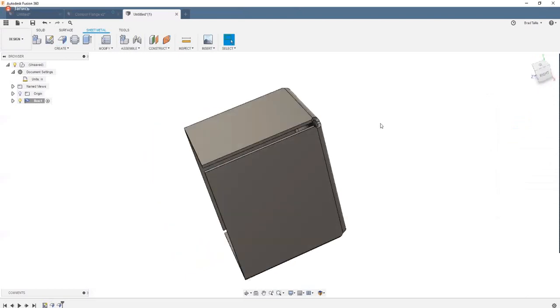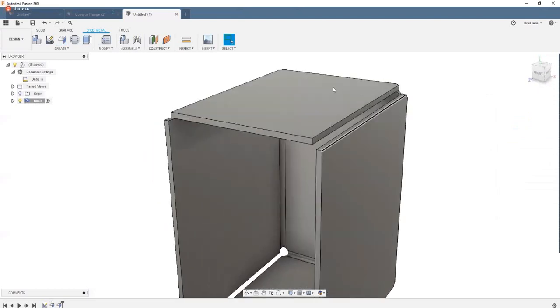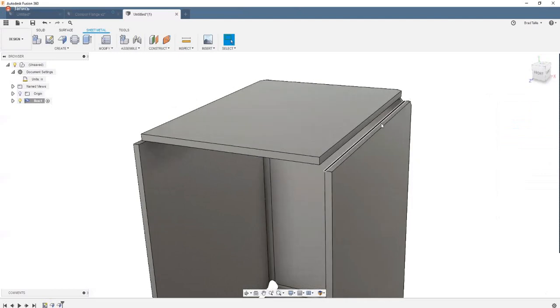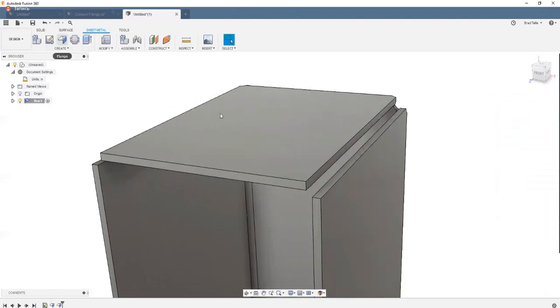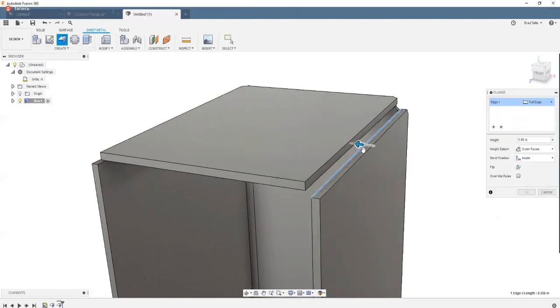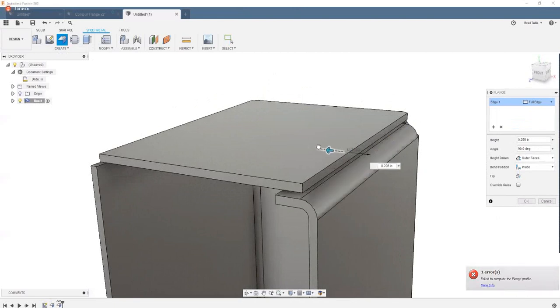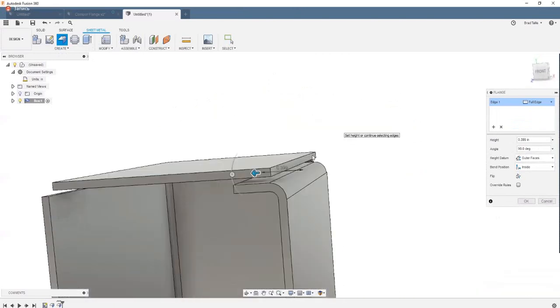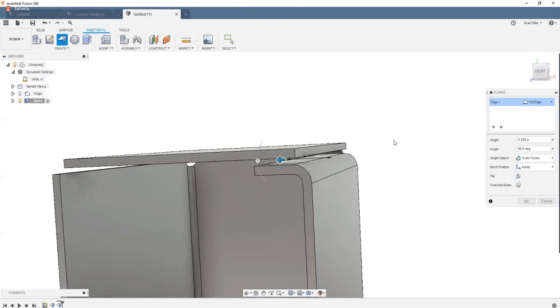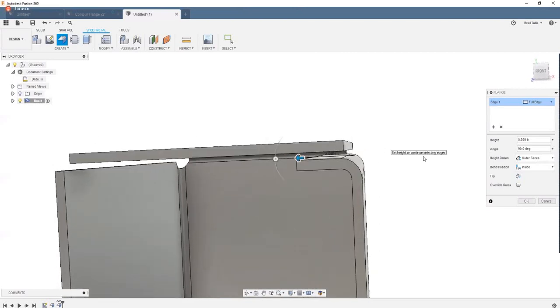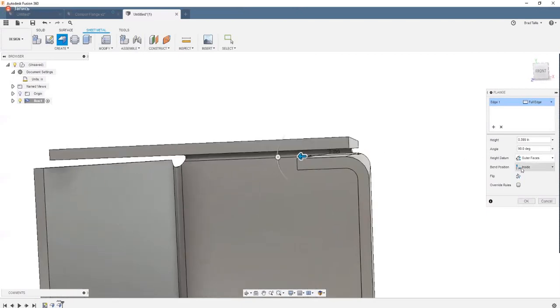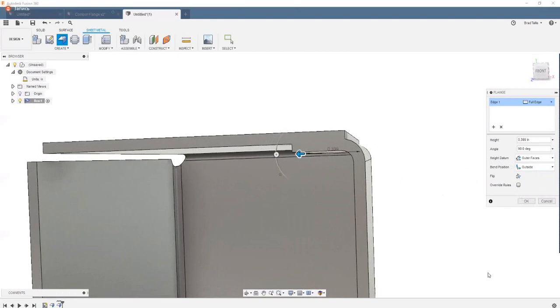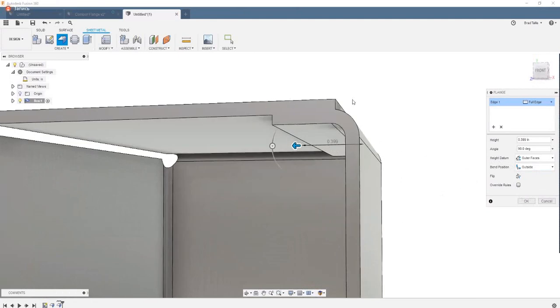Now, in the example I had loaded, there's a metal tab that goes over it, that holds this in place. So the next thing I'm going to do is create a flange and start to drag. And you're going to see an issue suddenly appear. Okay. I want it to go up and over, but in this case, it's coming underneath. So maybe I don't want the inside position, I want the outside position. But again, notice what's happening. In fact, I get a warning. It says it's intersecting the body, so this physically couldn't be manufactured.